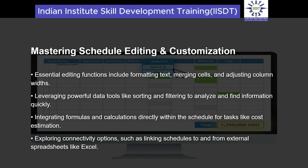The capabilities extend even further into calculations. We can add a calculated column to a room schedule that automatically multiplies the length and width to give us the area. We can then add a total row at the bottom that sums the area for an entire floor. This ability to perform calculations directly within the design environment is incredibly efficient. Furthermore, many platforms allow for interoperability, enabling you to export schedule data to Excel for further analysis, or in some cases, create a live link where changes in the spreadsheet can update the schedule within the model, bridging the gap between design and data management.